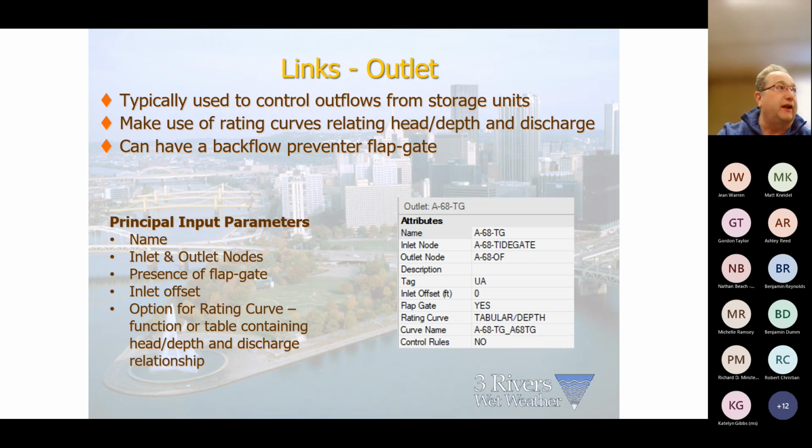It's, again, just like any of your other conduits. It's at that upstream manhole. What's the elevation of that pipe that's leaving, or the flap gate or whatever that you're representing with this element? Do not put a boundary condition on it out though.